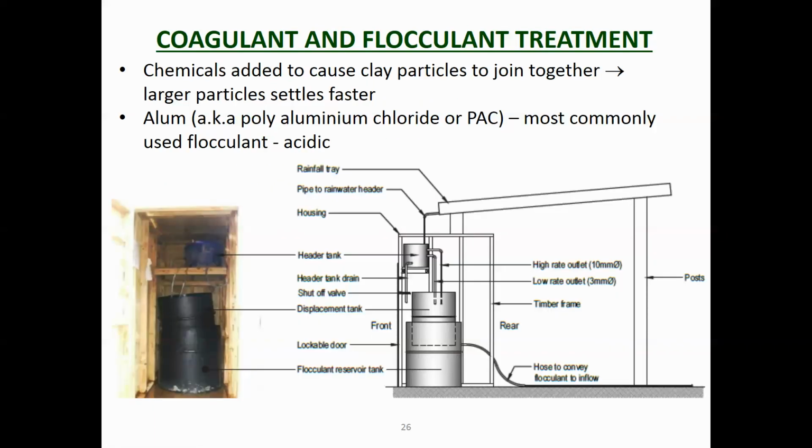So in Auckland, our clay particles are negatively charged, which means they repel each other. They don't clump together very well. Now, when soil particles clump together, they are more likely to settle. It's easier to settle them out. If they're just a whole lot of small clay particles, they're going to stay suspended in the water column for much longer. So if you can get the soil particles to clump together, then they're going to settle out quicker, and therefore the silt pond is going to be much more effective at removing the sediment.